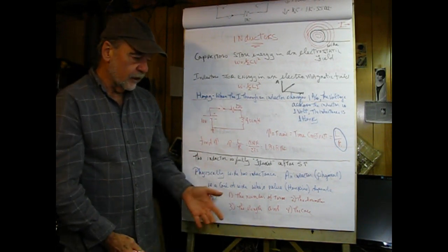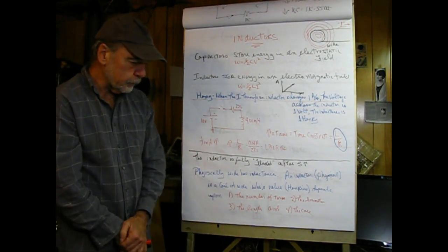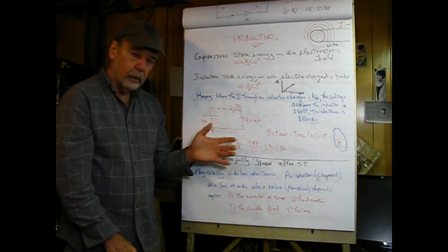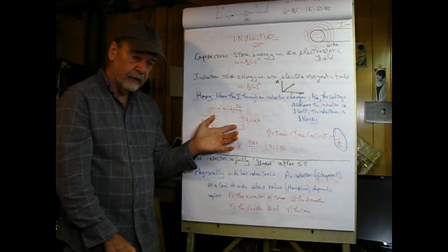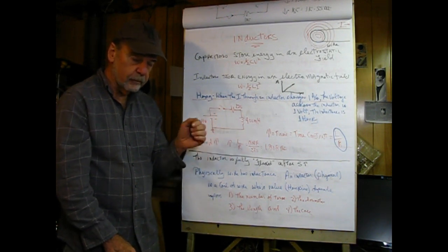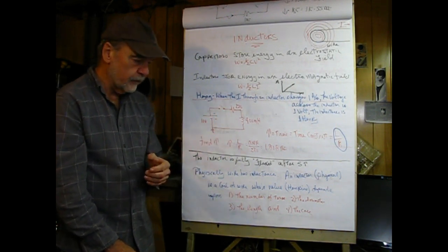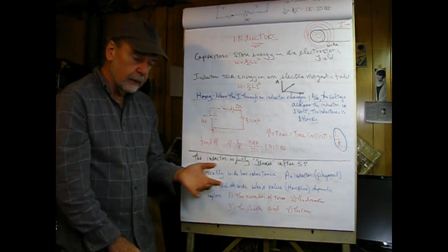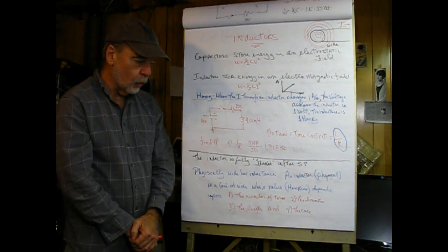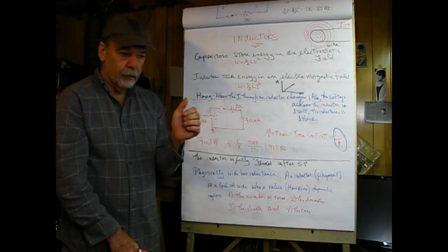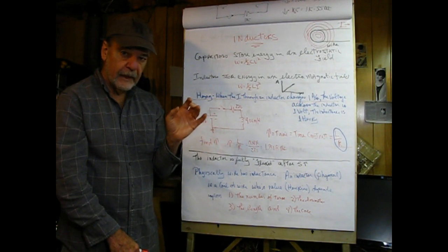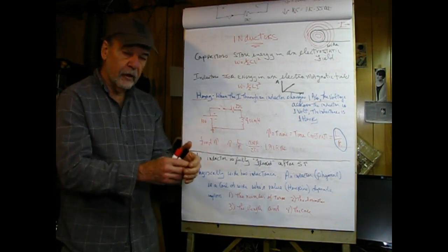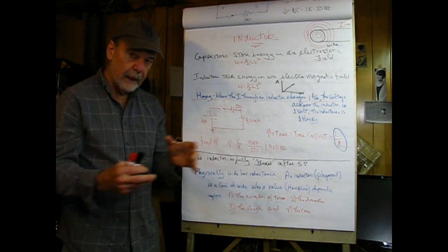Physically, a wire has inductance, and that's any wire. And we saw that in the capacitor diagram of a real capacitor with ESL, effective series inductance, and that's just the wire leads associated with the capacitor. So all wire has inductance in it. And sometimes in your home, in the dark, if you turn off lights or something, you might see a flash from the switch plate. And what that's caused by is the inductance of your house wiring is collapsing.